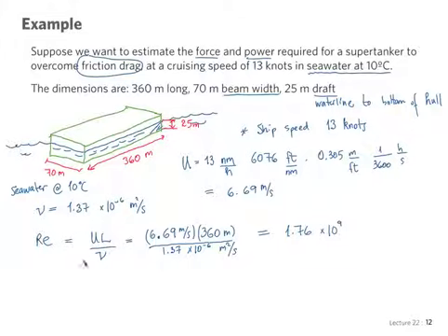We have the Reynolds number, so we're going to calculate now the coefficient of drag using the formula that we just presented for the mixed boundary layer. So it was 0.031 over the 7th root of the Reynolds number minus 1,440 over Reynolds.